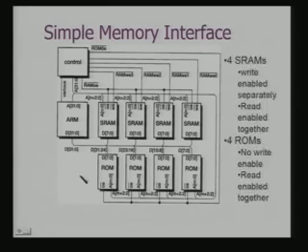What we see here is that these SRAMs are write enabled separately. So typically I have individual write enable signals. The individual write enable signals are not coming from the ARM core; they are to be generated by the interfacing logic which is here.